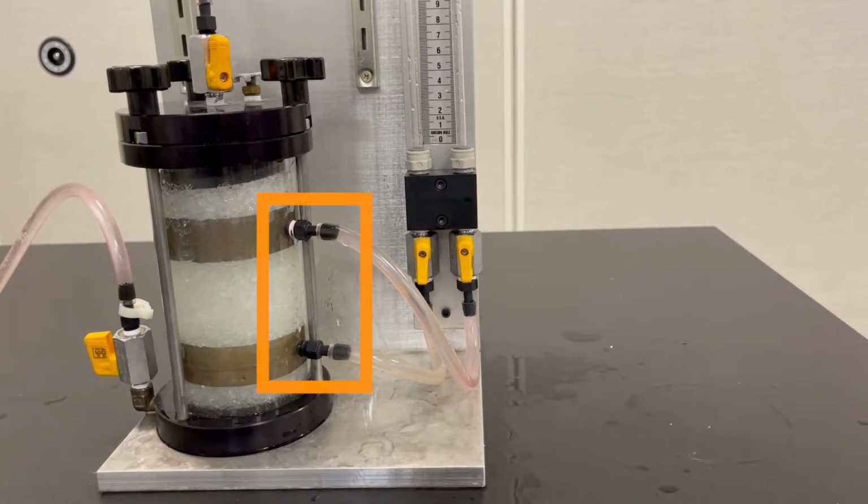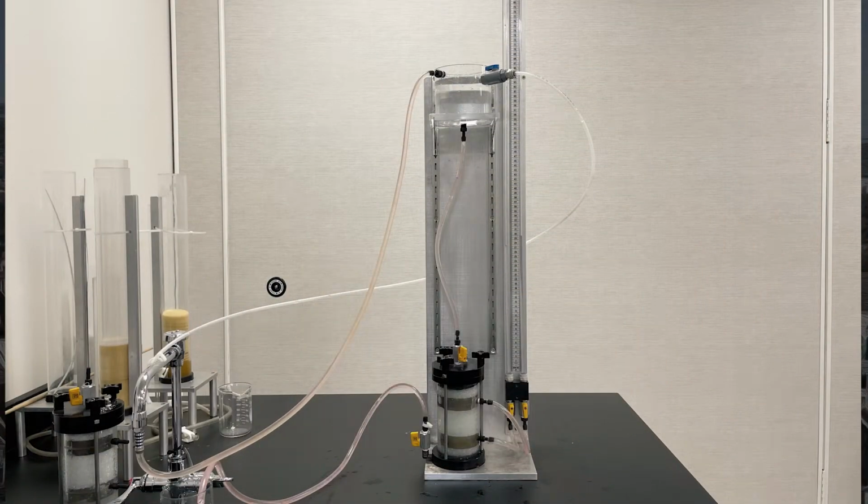These outlets are connected to the 2 manometers from which we will measure the difference in hydraulic head pressure. While Darcy used U-shaped mercury-filled manometers, our manometers are simply filled with the water flowing through the system. While it is a simple system overall, it is crucial that you ensure that the water is flowing at a steady state and that your media is fully saturated before you begin any experimentation.